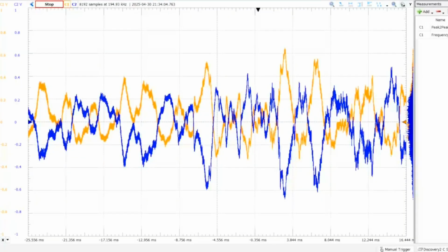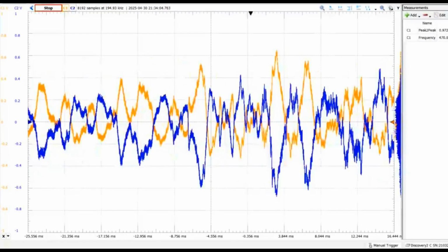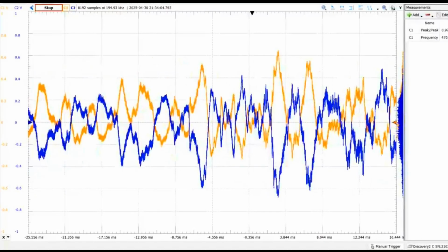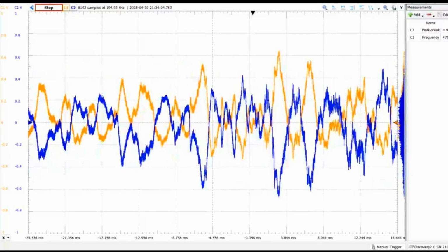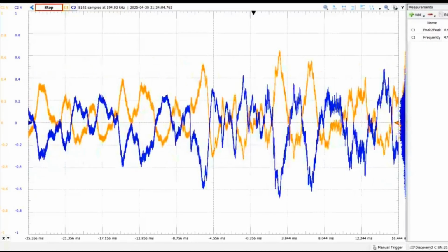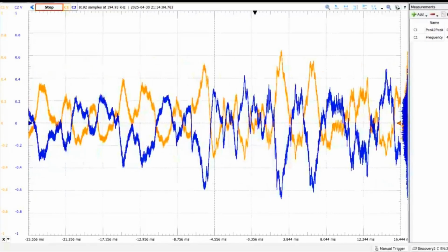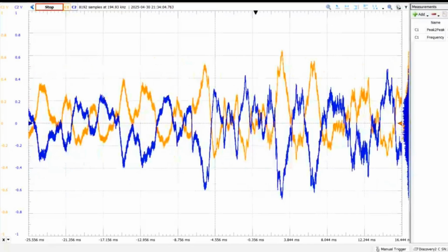All right, so as seen in the waveforms here, the output, which is the blue, closely follows the input audio coming from the iPhone 5S, indicating that the amplifier successfully modulates and reconstructs the audio signal through the PWM and filtering stages. Minor differences in amplitude and slight delays between the input and output are expected due to filtering effects, component tolerances, and MOSFET switching dynamics. Overall, the output waveform demonstrates that the system is highly capable of reproducing the original audio content with high quality, while efficiently removing high-frequency noise introduced by the PWM switching process.